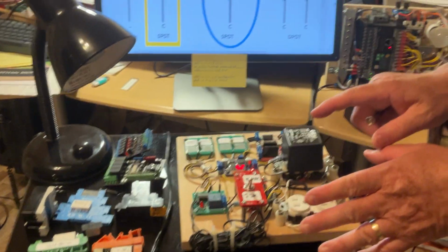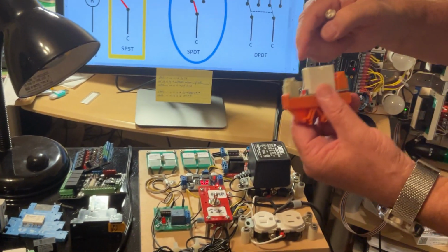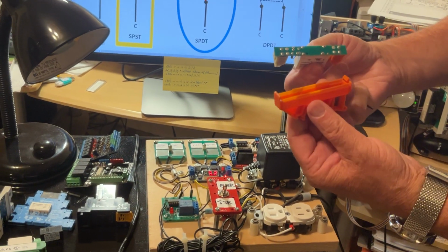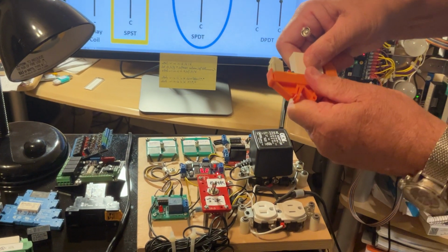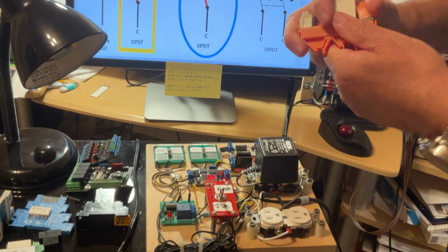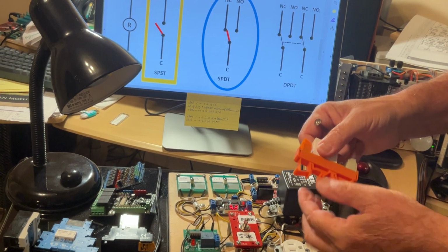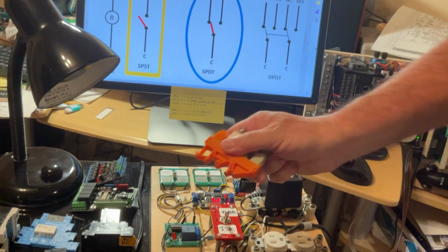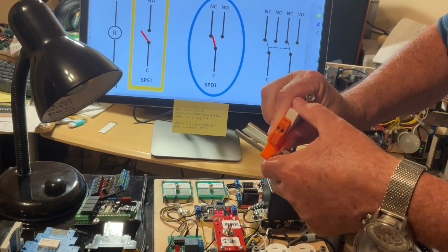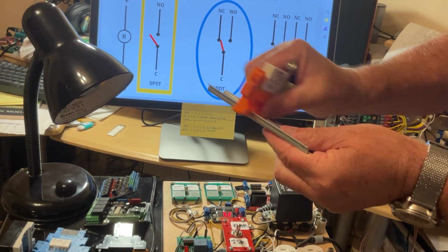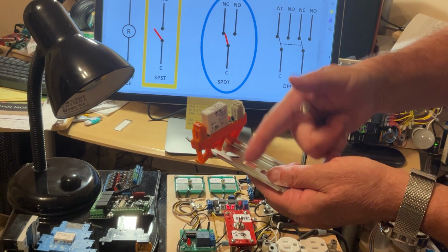Now I'm going to focus on the PCB relays. So I pick up the one we discussed before with 4 contacts. It's an industrial one. If you place it here on a support, it doesn't fall anymore. That plastic support has only one purpose: to allow you to place it on a DIN rail, so you can move it along and place a lot of other similar relays one after the other. Okay.